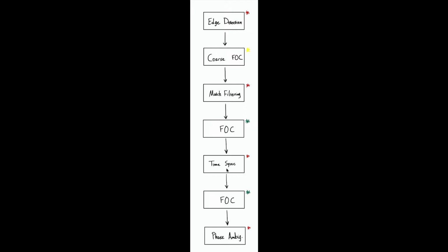Now, after getting the samples, if I didn't do this step here, I have some frequency offset that needs to be compensated. I can do this at the sample rate here, and this method is FFT based, and it's very similar to this method here. We will discuss it and see it. We will see both methods, the coarse and the fine frequency offset compensation methods here.